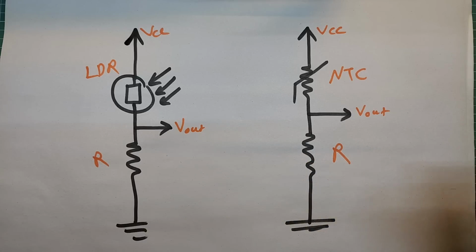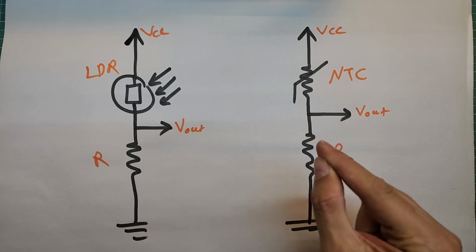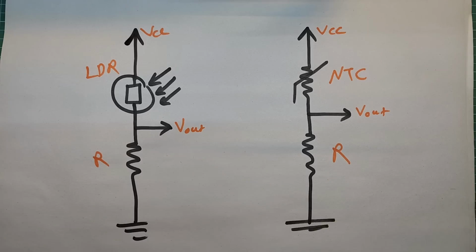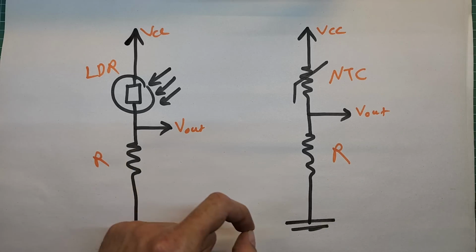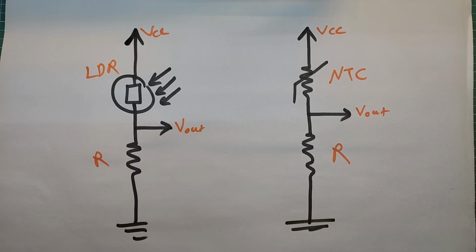So it is likely that the voltage of the sensor here or here will drop to 0.7 volts, the trigger voltage of the BJT, and stick to that voltage. In contrast, if you want to use the voltage here or here to trigger a device with high input impedance like a MOSFET, it will be okay. Yes, that's right. In this circuit, the sensor voltage will be able to trigger a MOSFET without affecting the sensor voltage itself, and it will definitely work.